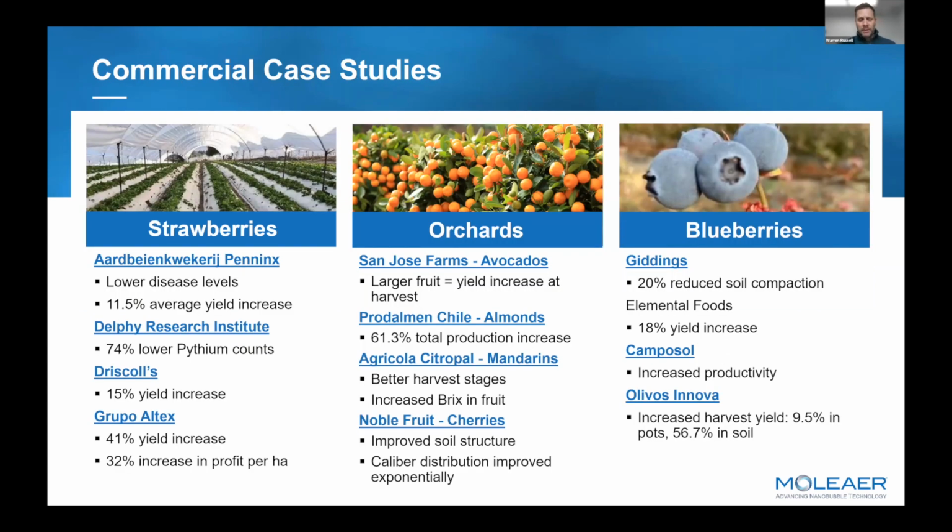Because this is an aqueous solution-based system, we're sizing our systems based on the water that we're actually treating. That can mean a volume of water in a reservoir, in a tank, or ultimately the gallons per minute or cubic meters per hour going through a pumping system. We're focused on how much water we're treating and how much time we have to treat it.